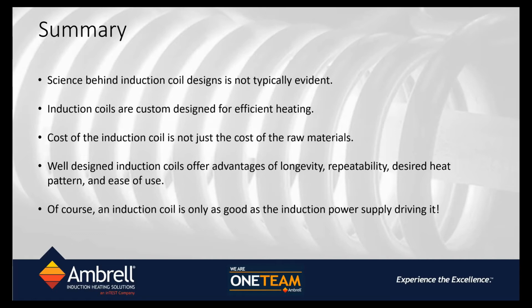When you have small localized sections to heat, you tend to gravitate towards higher frequency power supplies. And the reason is economic. It's cheaper to make lower frequency power supplies that are able to deliver a lot of power for large part heating. So that is the answer to your first question.